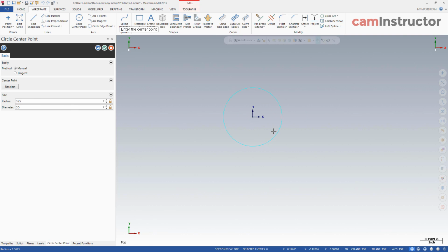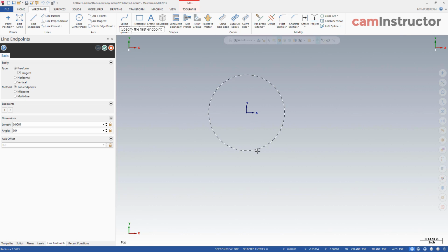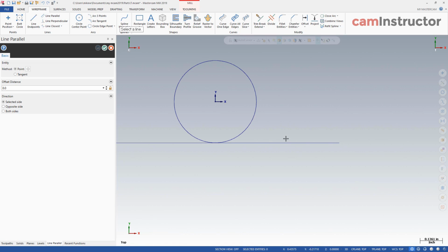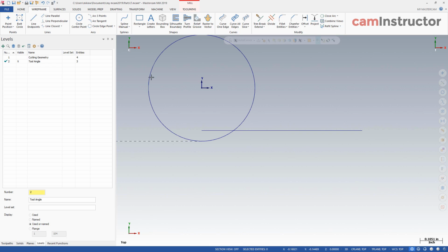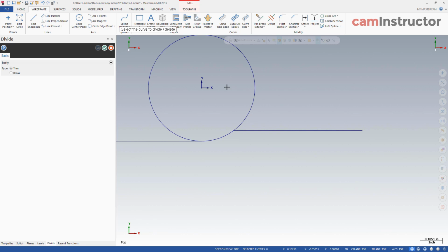And we're going to basically try and show what's going to happen in the cut. So that's the material the cutter's left behind. We're doing a climb milling cut. Cutter rolls this way, so we're moving in this direction. And in my toolpath, I said I was doing a 50 thou step over. Okay, so basically I've got this line 50 thou higher than this line. We'll just trim this guy up so it looks better.